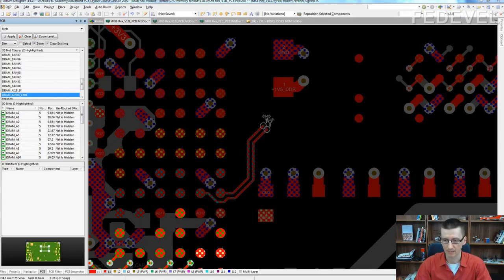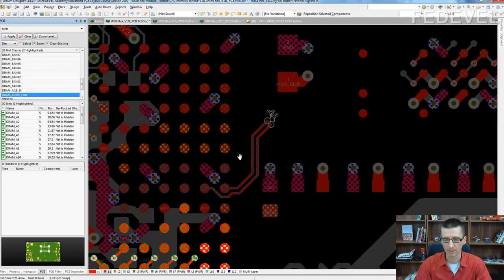The thing is, because signals travel at different speeds on the top and bottom layers compared to the inside of the PCB, do not make this fan out too long on top or bottom layers, because this may influence the time when these signals will arrive. Try to make them as short as possible.